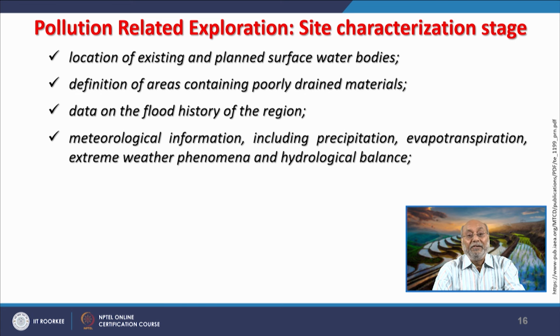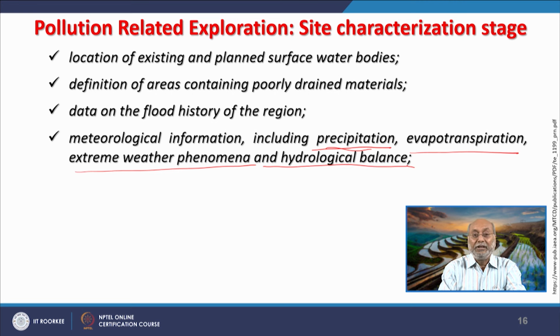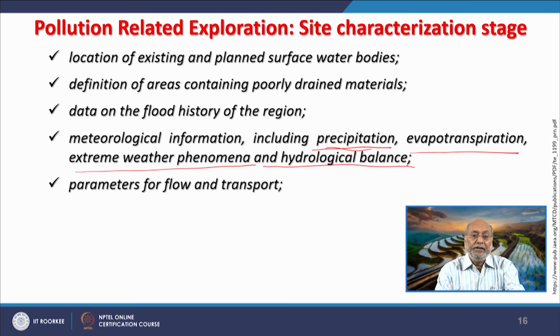Then meteorological information: what kind of rain we are getting, precipitation, evapotranspiration, extreme weather phenomena and hydrological balance. What I am trying to say is that extensive knowledge is required before any site is chosen, especially for hazardous waste. Even for municipal waste, extensive requirements are there.